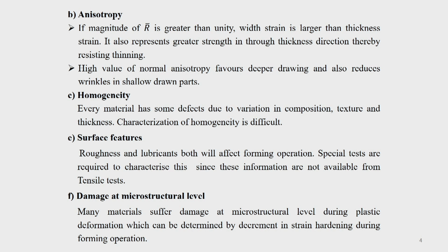Now, inhomogeneity, when you talk about it, see every material has some defect due to, say, variation in composition. It may be due to variation in the texture and it may be the variation in the thickness, okay. Or maybe internal defects are there, maybe gas porosities or pinhole porosities or some inclusions, all these things are there. So, homogeneity is something you cannot quantify. Okay. So, quantification of homogeneity is very difficult.